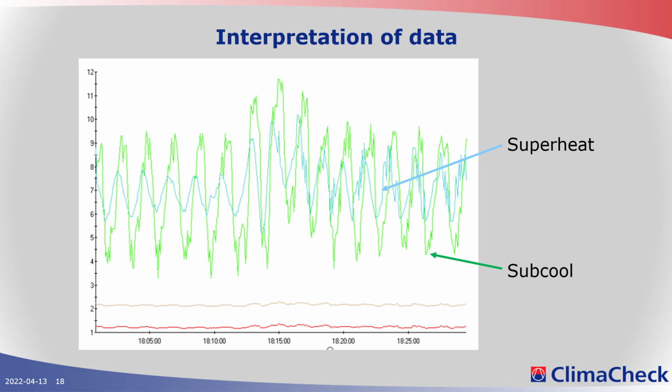But many times you see receivers that are extremely not cost effective, because it would have been cheaper to add volume to your condenser, just a bigger condenser, which would be useful surface and not requiring the safety valve. And many times receivers have sight glasses that increase leakage risks and so on. But in principle, if you increase your superheat, you move refrigerant to your condenser side, which will increase the subcool.